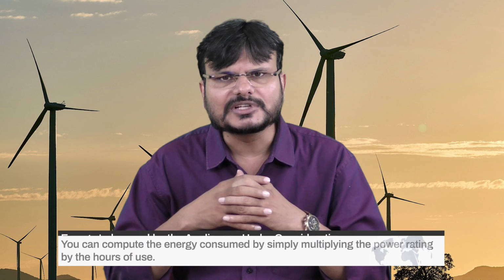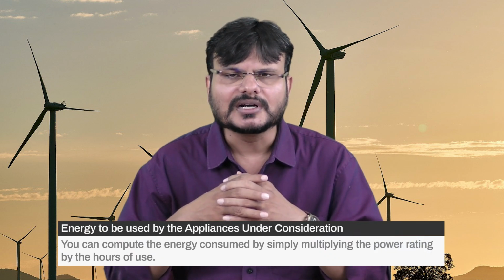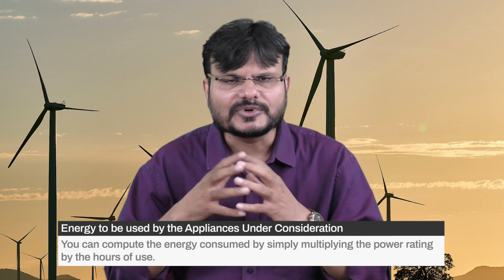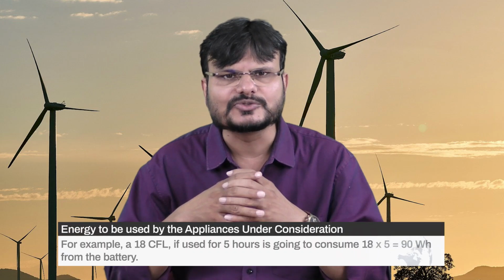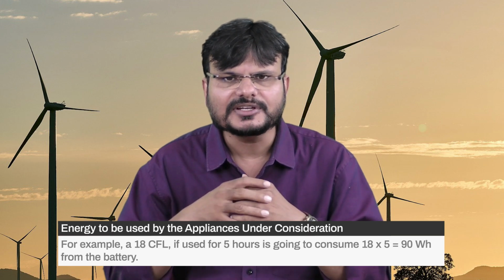You can compute the energy consumed by simply multiplying the power rating by the hours of use. For example, an 18 watt CFL, if used for 5 hours, is going to consume 18 into 5, that is 90 watt hour from the battery. In a similar way, you can work out the total energy requirement. Now we have to decide the storage capacity of the battery.